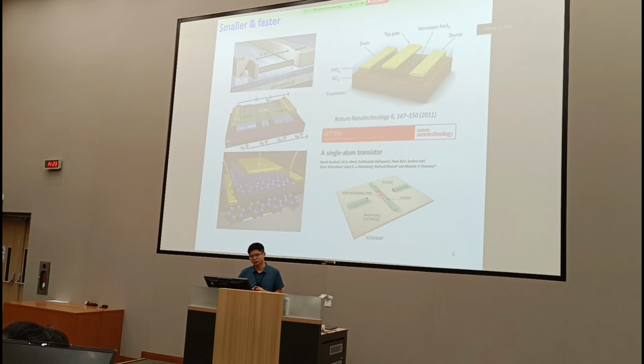This is the so-called single atom transistor. If you look at the whole structure, counting the electrodes and also the gate, the physical size is much beyond one atom size. But for the active component inside the channel, the current is modulated by a single phosphorus atom, which is implanted in the surface of silicon. So this is a very nice concept demonstration.